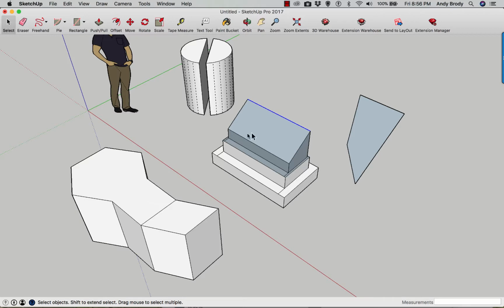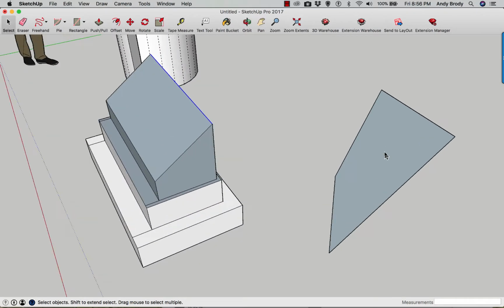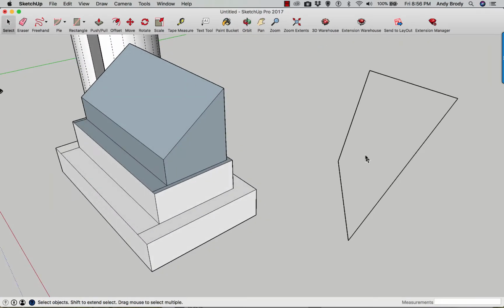If you want to select an object and its bounding edges, a face and its edges, you'll have to double click on it. You see how if I click just the center, that's just the face. I'll delete it. And now you just see lines. If I double click on it, now I just have the edges and the center face. See, I'll delete them all. Finally, if I double click on it, but then hold down Shift and get rid of the face, I could delete these edges. What you'll see, though, is a face cannot exist without edges, so I can't delete just that.